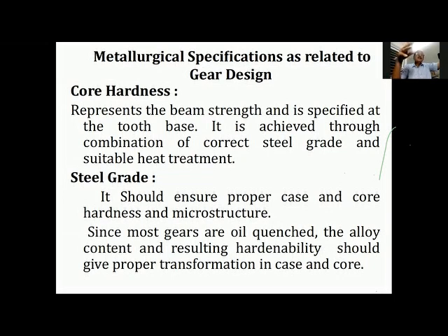Whereas the grade specification will be based on the requirement of the design. The steel grade should ensure that proper case and core hardness and microstructure are achieved by conventional quenching in oil.